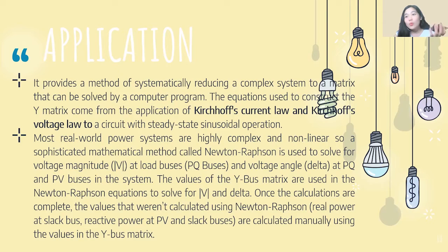So this Ybus application, or Ybus admittance, helps us systematically reduce that complex system into a matrix wherein we could use the equations to construct the Y matrix to come up with the basic application of the first and second laws of Kirchhoff, which are the KCL and the KVL, for a circuit with a steady state sinusoidal operation.